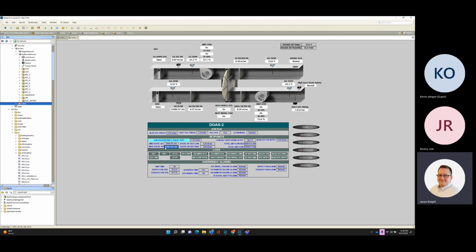The maximum amount of airflow is 12,961 CFM, and the engineer wanted the machine to run at 2 inches to meet that maximum static pressure set point, which is calculated right here. Does that make sense? What I did over here to the right is I calculated the required airflow.